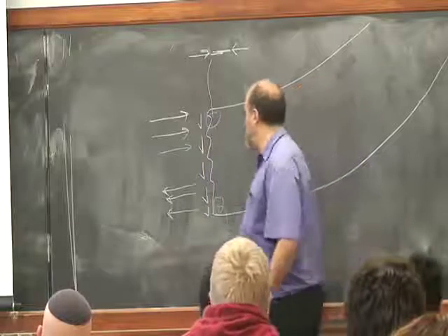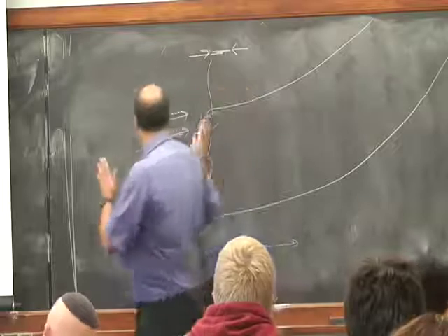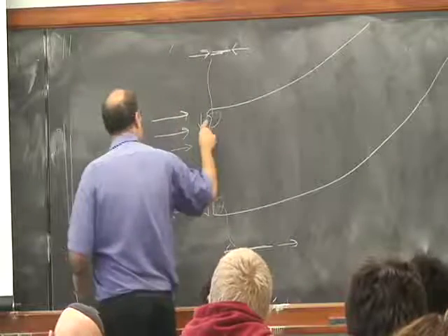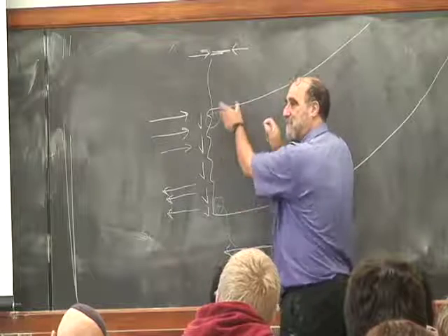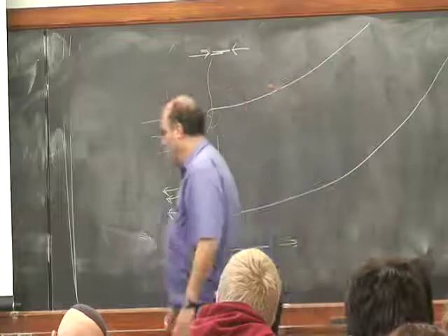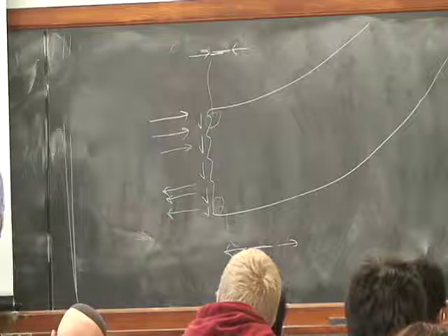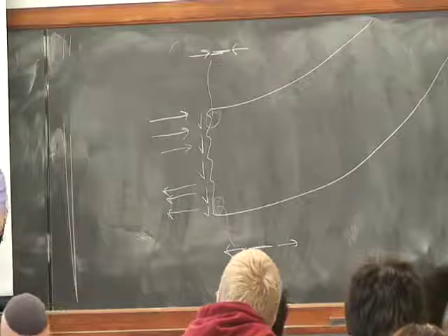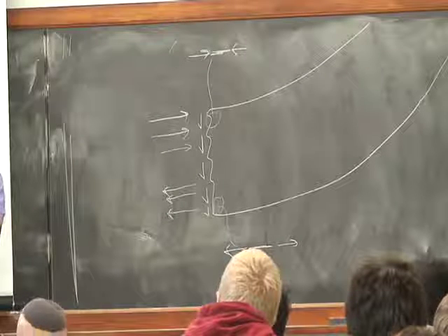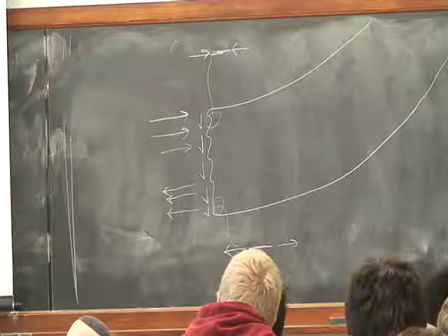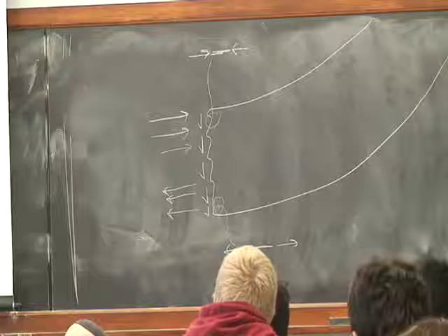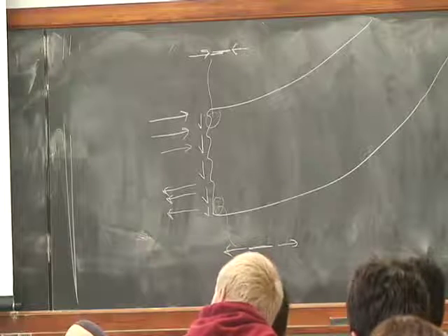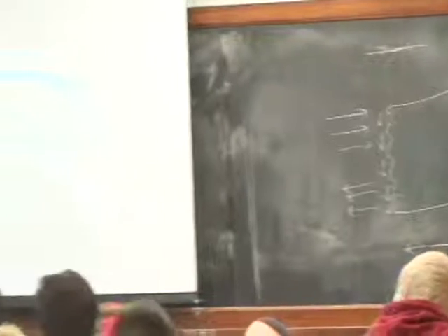And the rough scaling goes like this. What's happened in this little section here is we're doing this whole stack of tension and compression experiments on these fibers. And the question is how much do those fibers resist the overall bending of this overall beam? So here we have these fibers, and how much do they resist this?